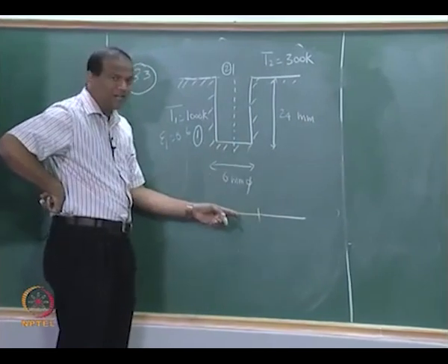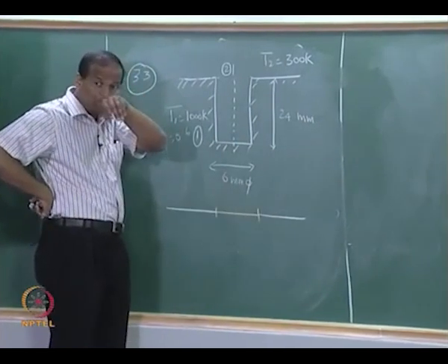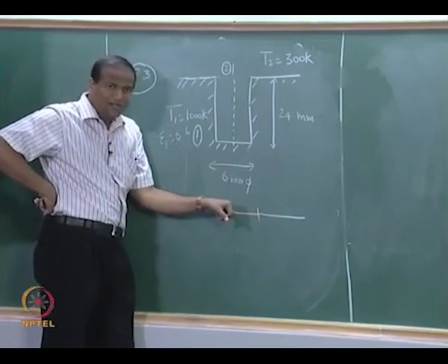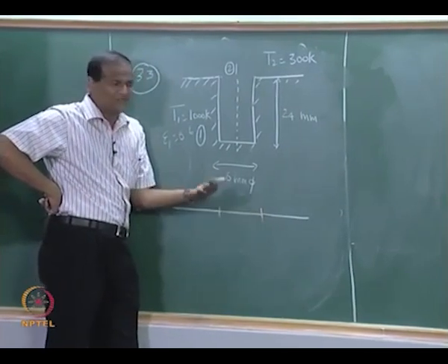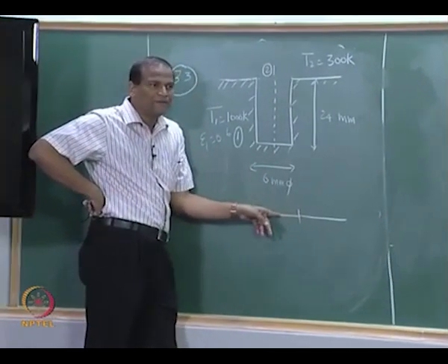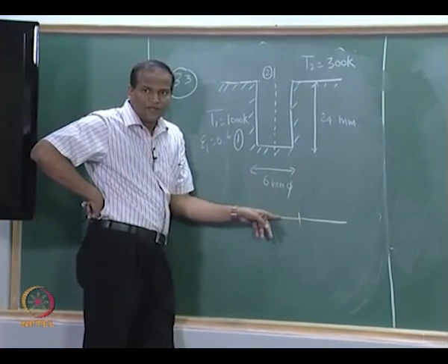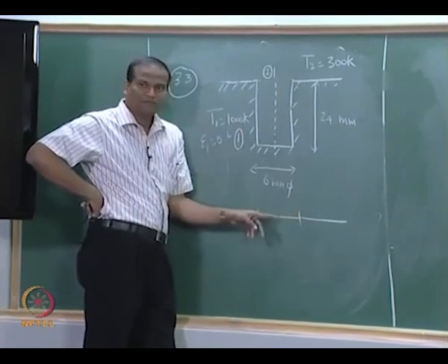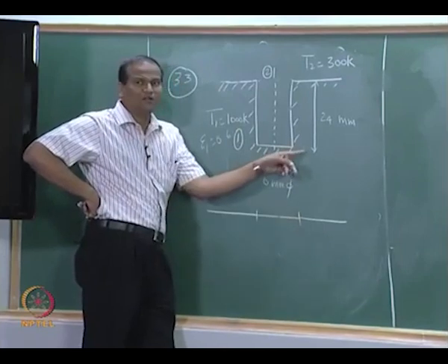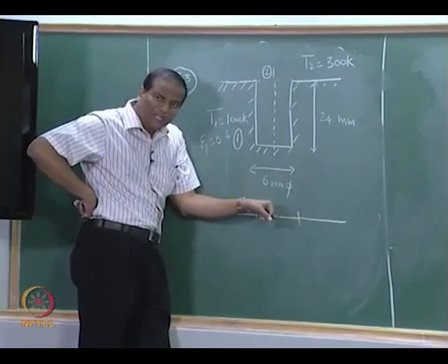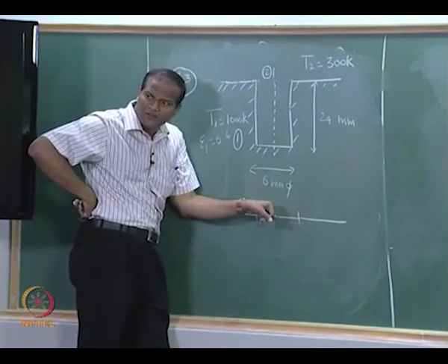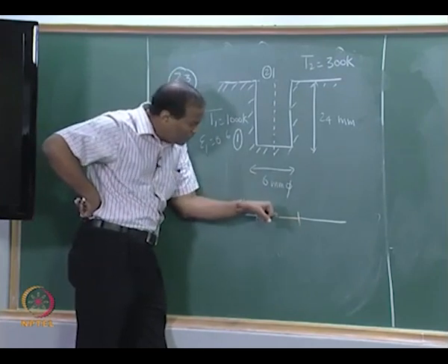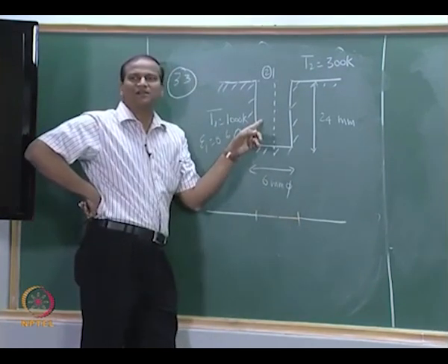This is basically a circle with a radius of 6 millimeters. But now I say this circle of 6 millimeters radius is a surface which is a black body. Now this is at 1000 Kelvin, it is also losing heat to the surroundings at 300 Kelvin. This will dissipate a certain quantity of heat to the surroundings. I want to see compared to this how much this will dissipate.